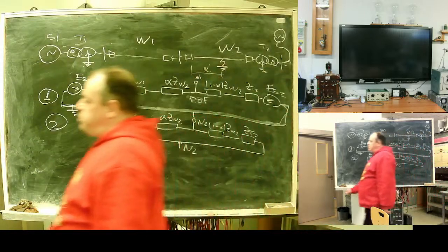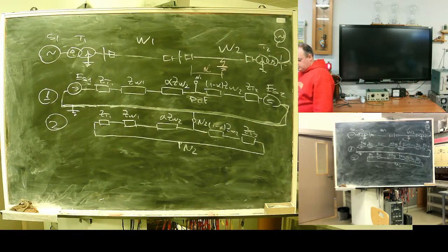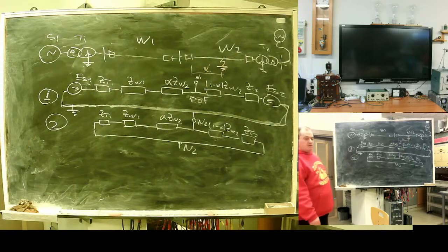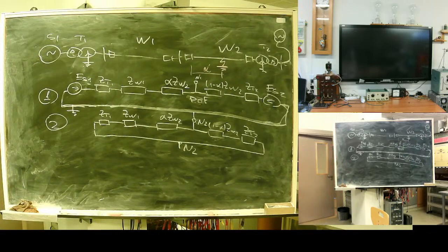Nothing works without the power. Nothing goes because there is virtually no circulating current in symmetrical regime. But in zero sequence regime, current will circulate. So delta connection forms a short circuit for the zero sequence.